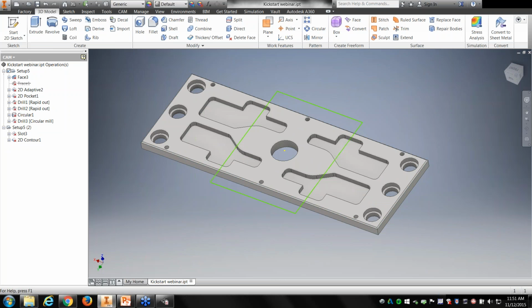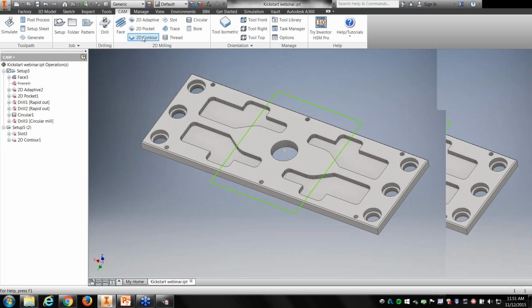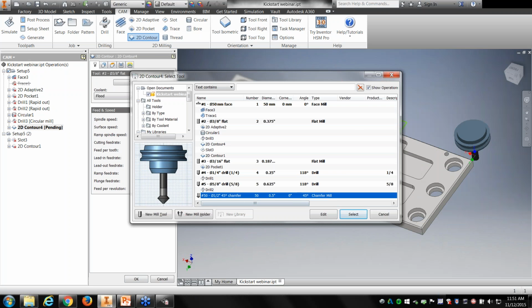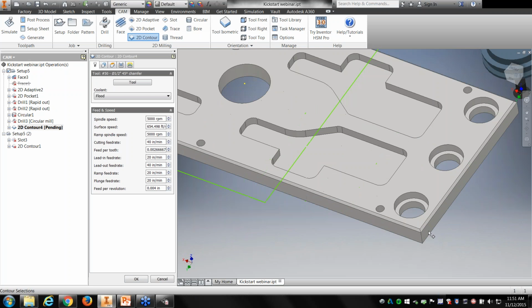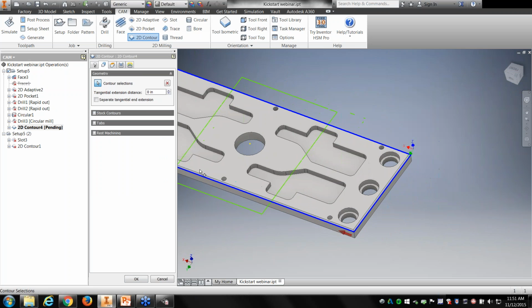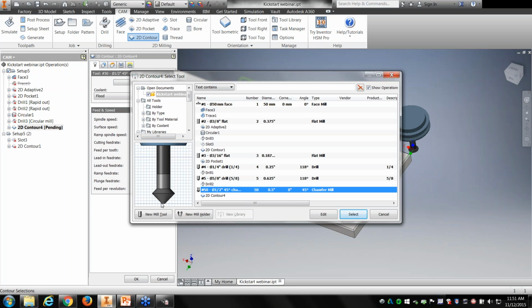Okay. Go back to the CAM chamfer tool. Once I have that chamfer done, I can select the lower chain of that, and it's automatically going to snap the lower section of that tool. So like this edge, it's going to snap that edge of that tool to that line.